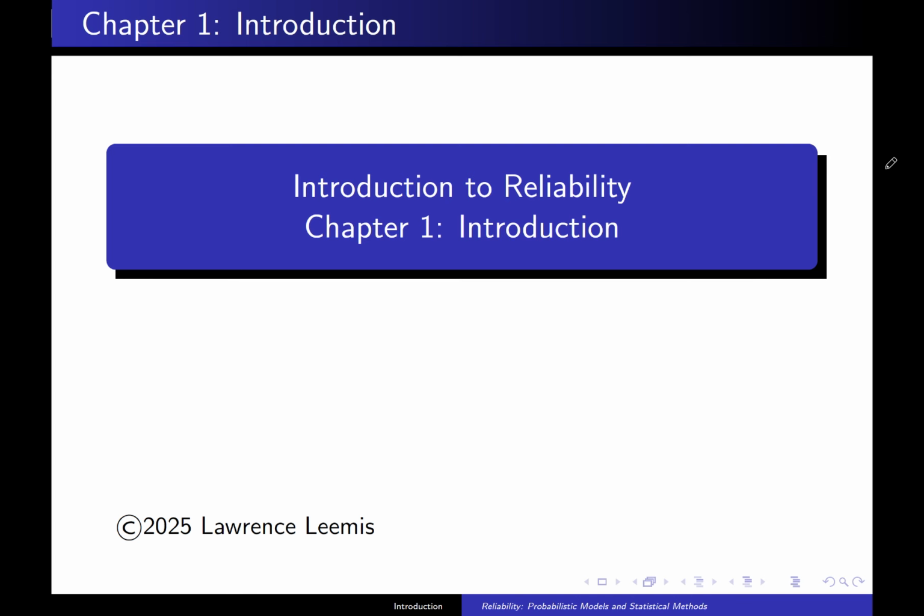Second question is, are there actions that we can take to improve the system reliability? One action is to simply use higher reliability components in the system. Another action is to redesign the system and, in cases of critical components, place those components in parallel to achieve higher reliability.